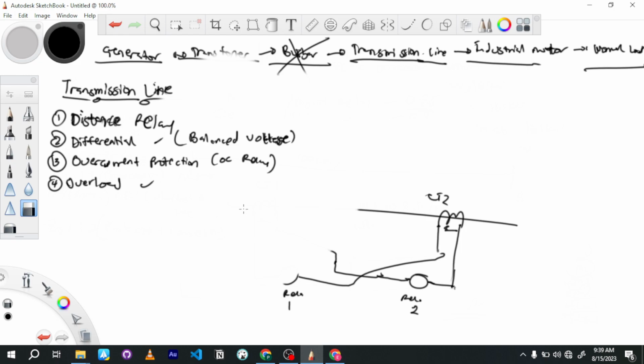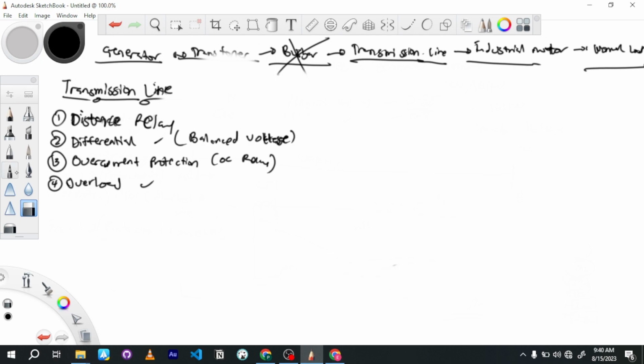One of it is that, let's say your generator is rated 5 MVA, and you as a consumer are drawing 5.2 MVA. When generators are rated 5 MVA, this is not a final end limit where going a point beyond it, the generator would blow up. No, it's a rated limit. It's the limit at which the generator can run for many years without suffering. 5.2 can be sustained, but not for long.